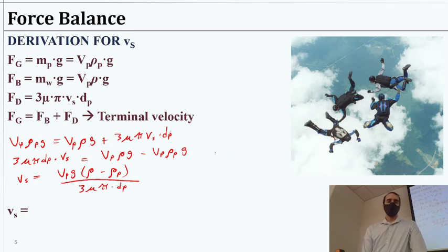We're also making some other assumptions based on the viscosity, the turbulence, things like that. We're assuming we don't have turbulent flow, just slow laminar flow, and that particles are not disturbed by motion in the water. So there are a few assumptions going on here, but overall it's just to simplify the situation.